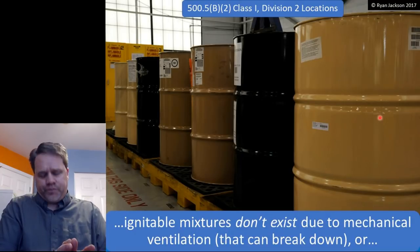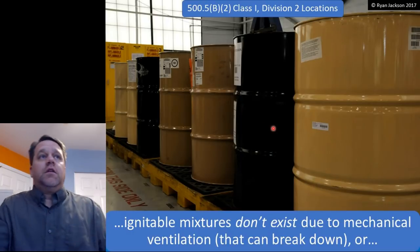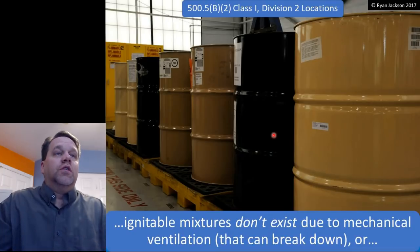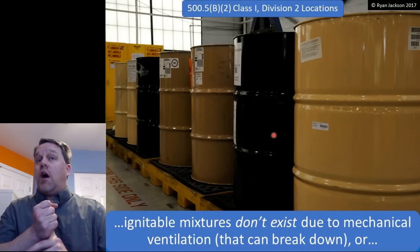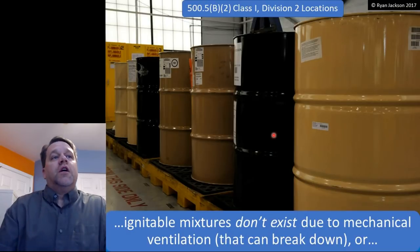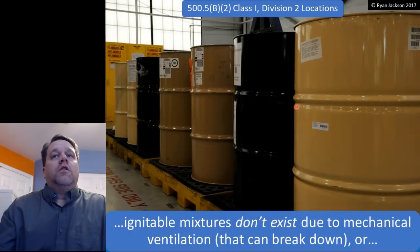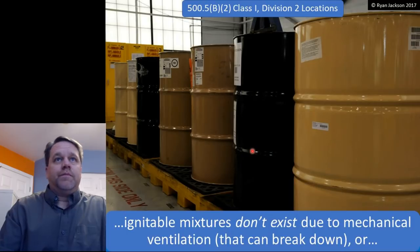Somebody drives his forklift into this barrel, and somebody walks in smoking a cigarette at the same time, right? That would be a Class 1 Division 2 location. Or if the ventilation equipment stops working and somebody walks in smoking a cigarette at the same time, that's a Class 1 Division 2 location, where the ignitable mixture is normally confined, or where the ignitable mixture is prevented due to mechanical ventilation.